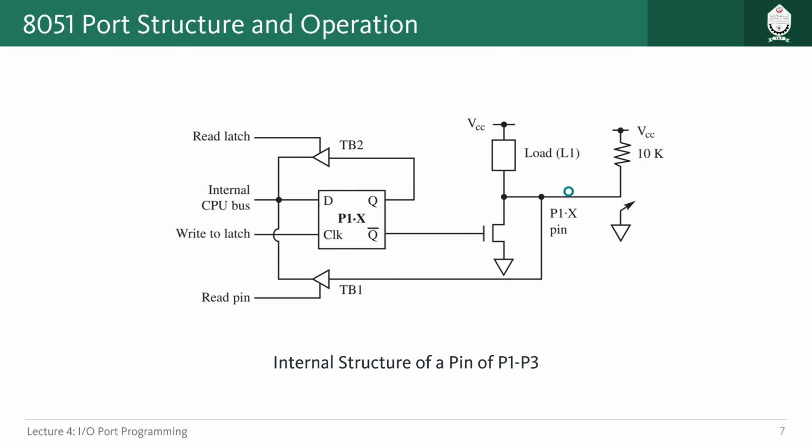So one of the examples is this. What we can do is connect a pull-up resistor through the 5 volts, so that this switch can be connected here or it can be open. Whenever this switch is connected like that, essentially we are getting ground. And if this is ground, if logic 0 is coming here and this is shorted, no problem is there, because both of them are ground, so a huge amount of current will not flow here, and that will not cause any problem, and we are going to get whatever signal we are trying to give here. That will go, right?